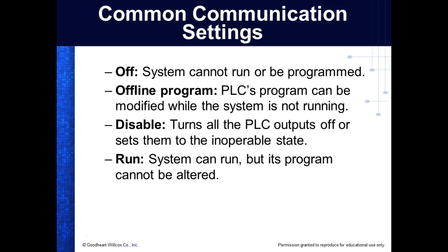The center switch is remote, which means you can switch it between run and offline from your application. And then you've got run. What gets people, you say what's the three positions, somebody says program, that's not really the program, it's actually offline. Understand that? We like to leave it on remote, and that way you don't have to worry about the switch. Because what happens, you try to download it, it's in run, and then it tells you you've got to switch it to program, you've got to reach up there and flip the switch, right? You understand?